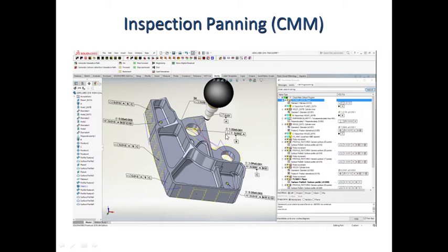or the design specifications. With the help of CMM, you also need to program the movement of this probe so that it can go to designated points. Otherwise, it is very difficult to manually take this probe to each and every point. So you make a program, a CNC program or NC code, with which it is going to touch the specified or pre-designated points to take the readings from there, and then the information is used for further processing like design, inspection, etc.